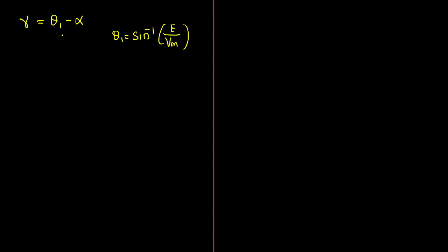It should be, wait guys, conduction angle, theta 2. Yes, it should be theta 2. Conduction angle is what they have asked. From alpha to theta 2 only, the diode will be in conduction. So you know how to calculate theta 1, right? Calculate theta 1, then explore the value of theta 2, that is pi minus theta 1, 180 degree minus theta 1. Then substitute that value here. That's all. Don't think too much. You'll be coming up with the answer.